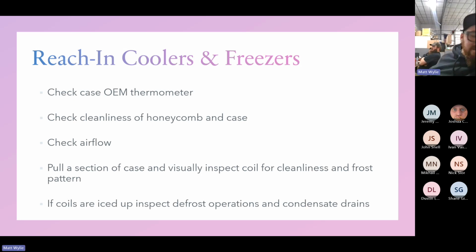Yeah, it's like if you have a heavy frost or, say, a light clear frost. Is that what you're talking about, Matt? Correct. And also, there are times where the whole bottom half of the evap is iced up, but the top isn't. I'm wondering if anybody has answers on diagnosing that.